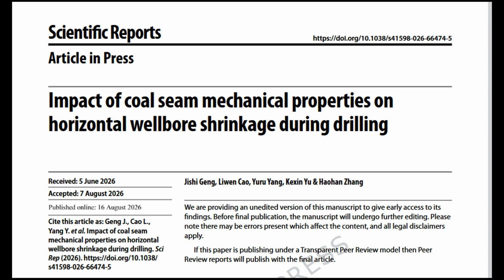It shows that radial stress increases as a power law function of the distance from the wellbore center, with the exponent controlled by the friction angle. The boundary condition is that at the wellbore wall the radial stress equals the applied wellbore pressure. Equation 8 gives the radius of the plastic zone, that is, the extent of the region around the wellbore that has yielded and entered the plastic state.